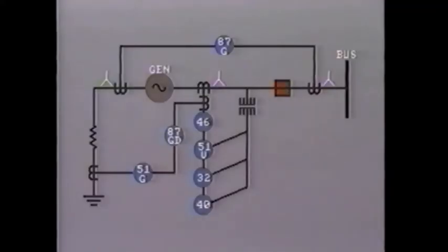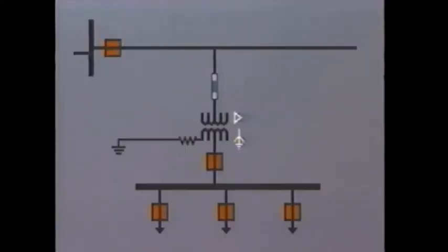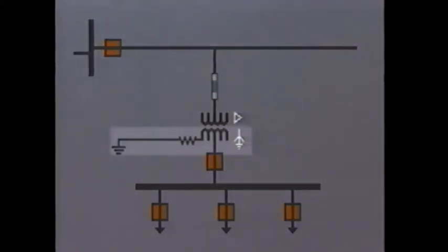In an earlier tape, you will remember we discussed the application of this relay to generator protection. Another typical application is with the distribution substation transformer, where the high voltage side is connected in delta, protected by fuses, and there are no CTs available. The secondary side of the transformer feeds through a breaker into the substation bus, from which various feeders are tapped off. The secondary side of the transformer is Y-connected and grounded through a resistor.